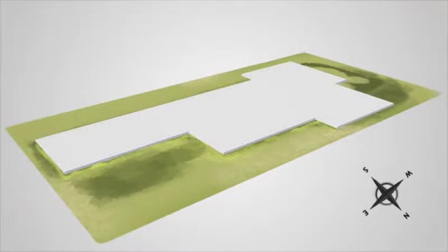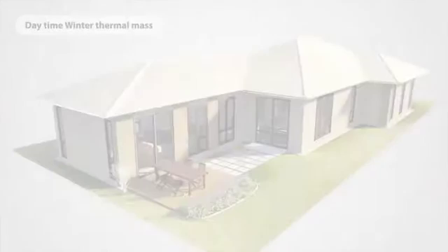Thermal mass is the ability to absorb, store and re-release heat. Thermal mass is heavyweight construction such as concrete or brick, but needs to be used on the interior to work as thermal mass. The advantage of having thermal mass in your home is that it moderates the indoor temperature in both winter and summer, as seen over the next few simulations.